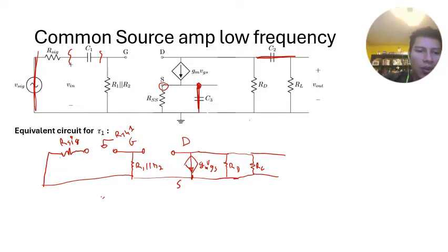Whenever I solve these circuits, I will always use an IX-VX test, even though you don't really need to do that in this case. You're going to get that it's just R sig in series with R1 and R2. That being said, using an IX-VX test will always work, so that's why I always do it. So I'm going to insert an IX, minus plus. So this is my VX, and then I need to figure out what IX is.